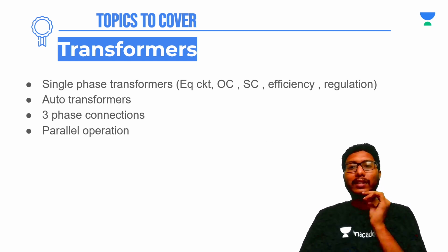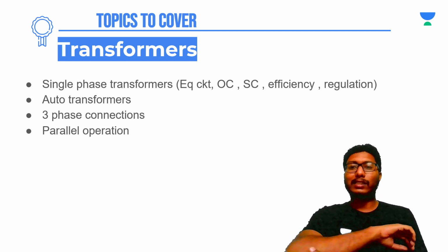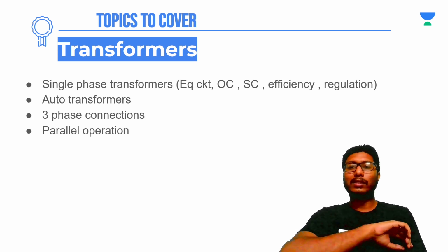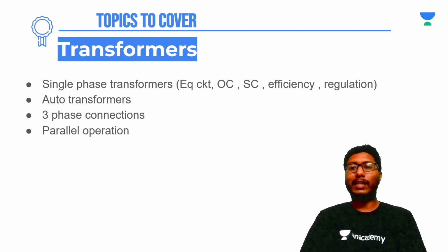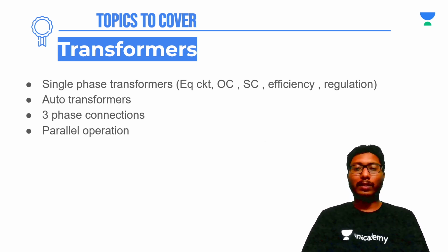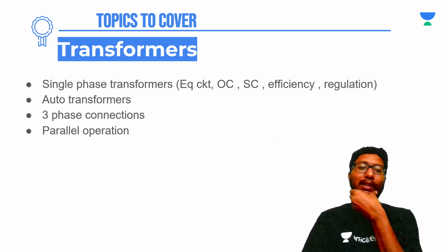So the important thing here is the proportionalities, that is, what hysteresis loss is proportional to and what eddy current loss is proportional to, that is thickness, frequency times in hysteresis loss and frequency square in eddy current loss. And B power x, if flux density is given as constant, then you can leave it, otherwise you cannot leave it. This B is proportional to V by f. So if V by f is constant, then you can neglect it. If V by f is not constant, then you cannot neglect it, and you should consider it while calculating.